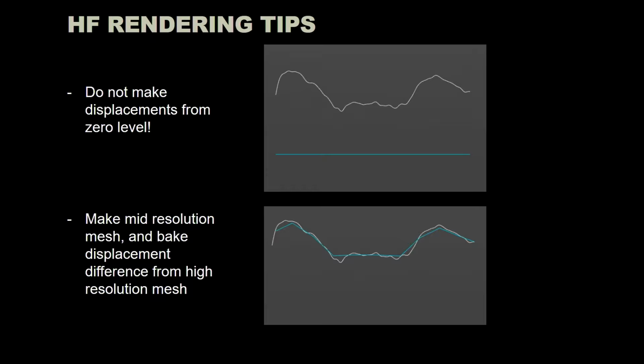And you will have a lot of issues with flickering shadows and flickering geometry. So instead, you should make a mid-resolution mesh and bake the difference.